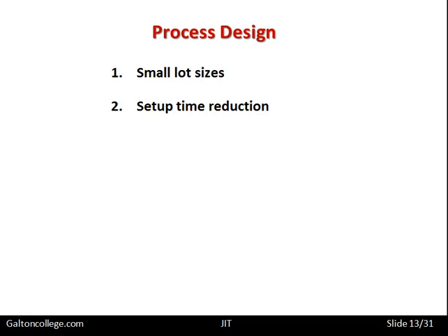It's all, in a sense, part of the JIT system. The machines are set up once and they run, and in running they move to the next machine. The next machine is set up once, and the next machine will process another part of the job and pass it on to the next machine, which has been set up once, and it'll process it. So it's not a question of having, let's say, 3 machines that have to be continually changed over, or X machines that have to be changed over. So we'd have machine A, B and C in sequence being set up once.